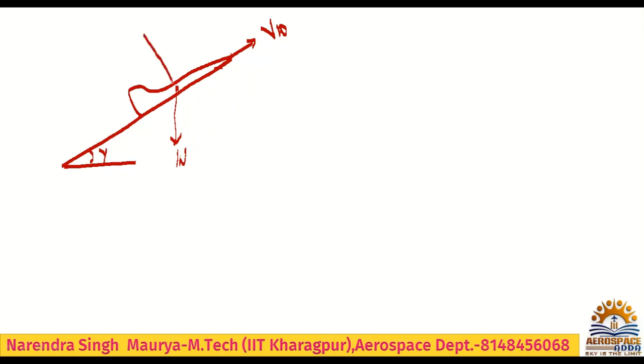So where will the lift be? This will be the lift force. Now where will the drag be? Drag will be just opposite to the forward motion. And you just check this. If this is gamma, then obviously this angle will be gamma. So we can write this is W cos gamma, and this will be W sin gamma. I'm doing this because in this way you can resolve the components, so you can equate. That is our basic mathematics.